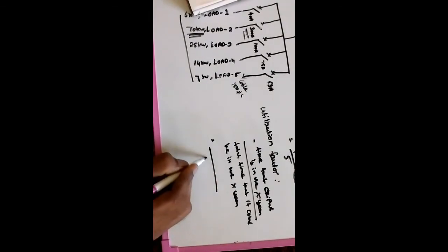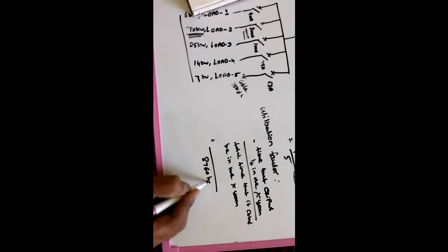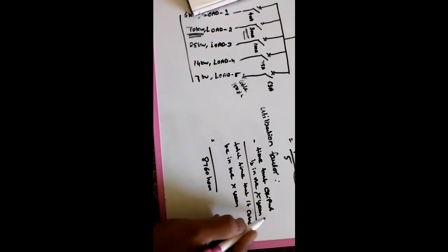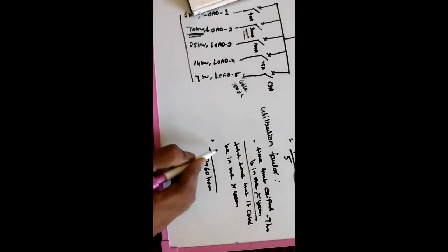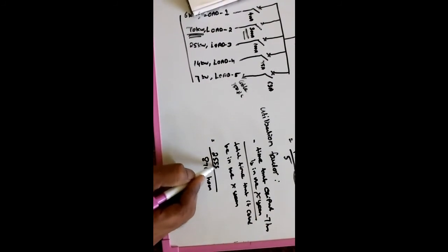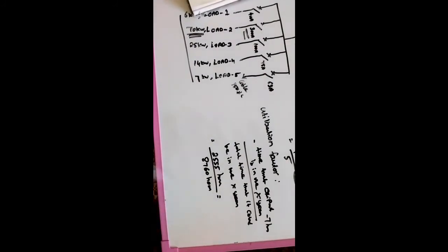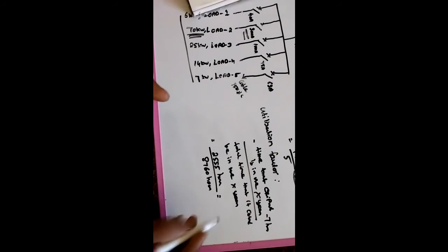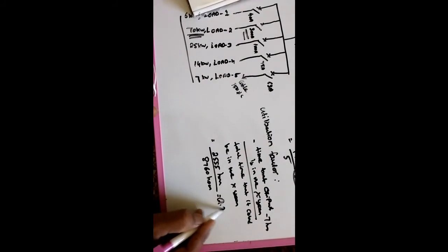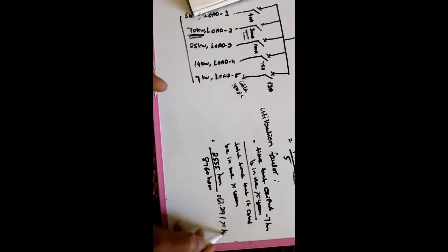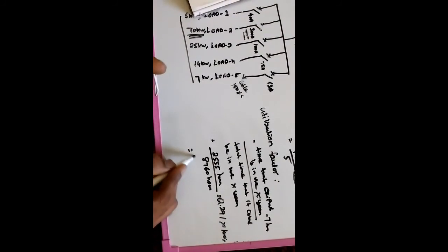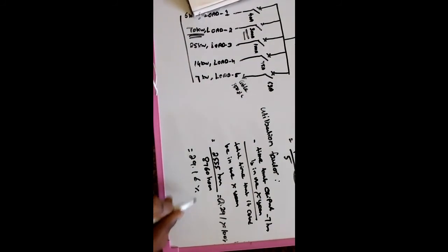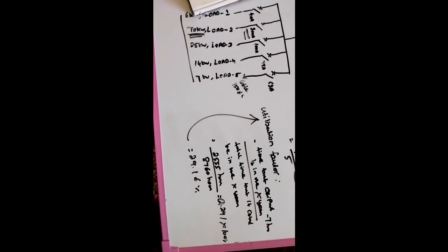So 8760 hours per year, and per day we use it for 7 hours, so 2,555 hours. This is called the utilization factor, 0.2916. Calculated in percentage, 29.16% utilization factor. This is a very important term for power systems.